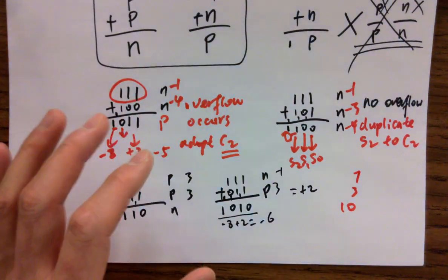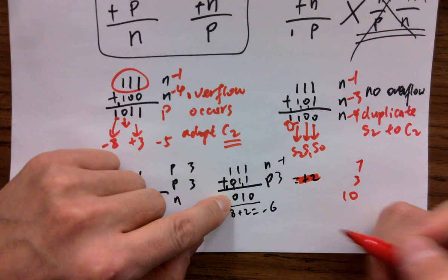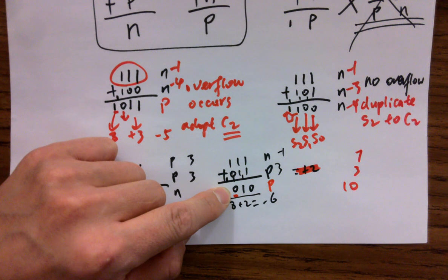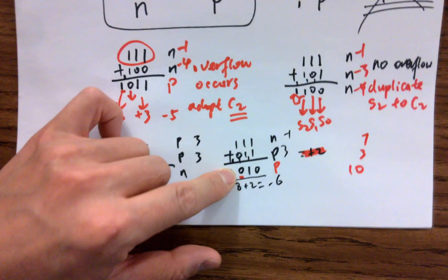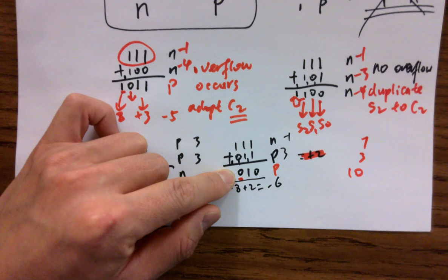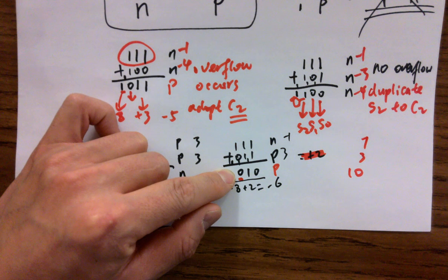Now let's come back, see if this is going to make it happen. Okay? Overflow or not? Yes. By looking at this guy. NP, P. Right? NPP. Overflow or not? No. Why? Doesn't satisfy any of them. Overflow or not? No. So in your Verilog, always think about it. Why we set up these rules? Because it's super easy to implement in Verilog. It's just simple if statement. So if overflow, then do what? Do a concatenation, right? You put the C2 over there in front of it, with a curly bracket. Okay? If no overflow, we put S2 in front of it. Just S2 and S2 as whatever the rest. Okay?